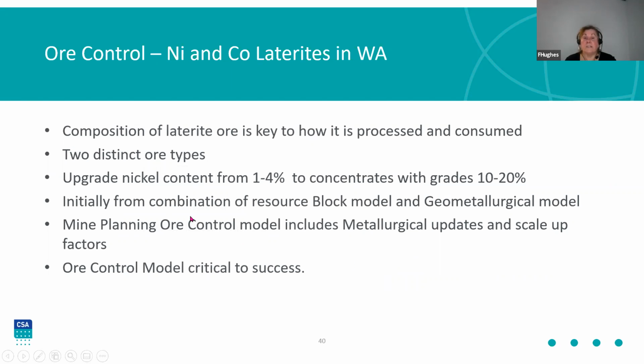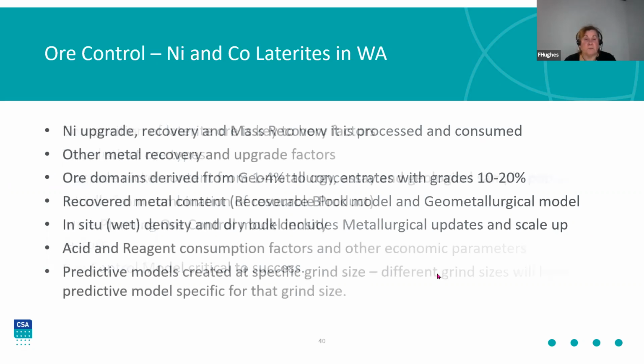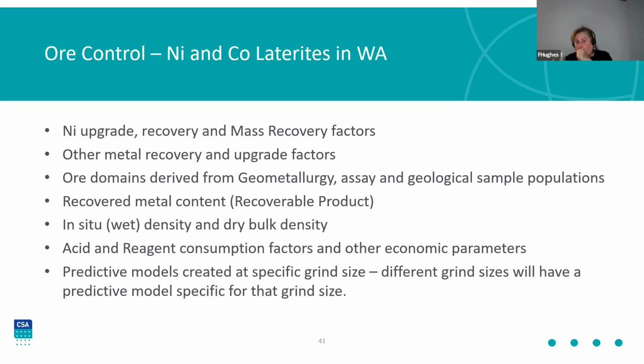The ore control is ideally a combination of using the resource block model and the geomet model to come up with predictive equations for identifying things like the nickel recovery and nickel upgrade and other elements like magnesium and iron that have impact on the recovery of the nickel out the back end. Mine planning ore control would also include metallurgical updates and plant scale-up factors. So there's an awful lot of information that's required to really control what's going on there, such as these factors that I've just been speaking about.